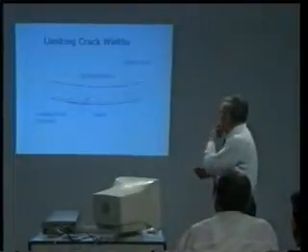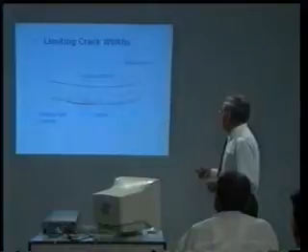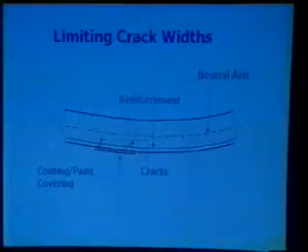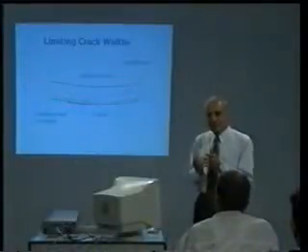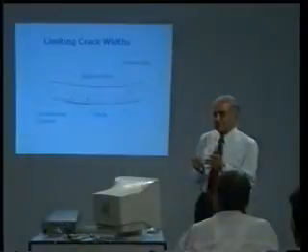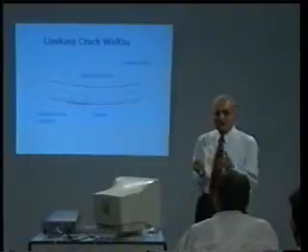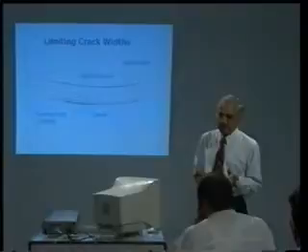So, at such locations, you must provide a proper coating or a paint covering, and that coating should be elastic enough to cover the crack width. So, that should have crack bridging capability and not be a rigid and inflexible coating.